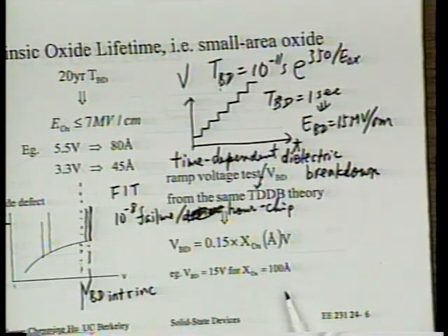Usually, most likely what's wrong with it is in the LOCOS or other isolation region, you have a thin band of oxide. That happens very often, all right? In isolation, the field edge of oxide, your oxide is thinner. So you don't have 100 angstrom. In fact, you can even work backward. If instead of 100 angstrom, you constantly see 90 angstrom, you can suspect that at the field edge, your oxide is actually 10% thinner than what you think. Sorry, if it's not 15 volt, you see, let's say, 12 volts consistently, 20% lower than the 15 volt you expect. You can expect you probably had a thin band of 80 angstrom oxide.